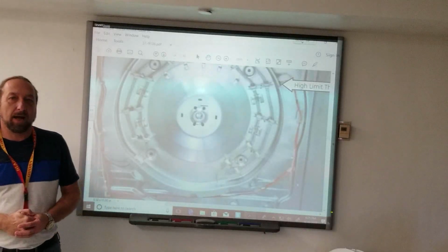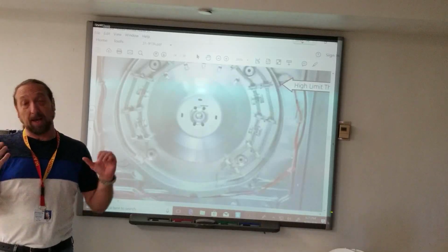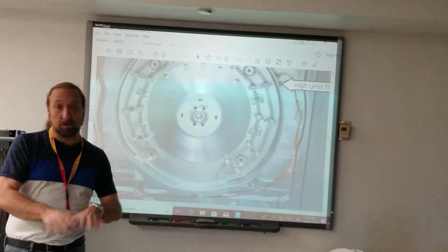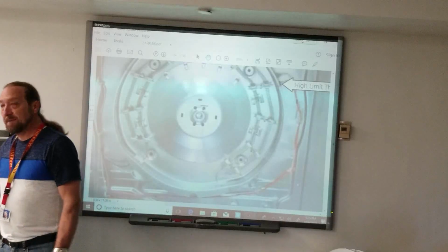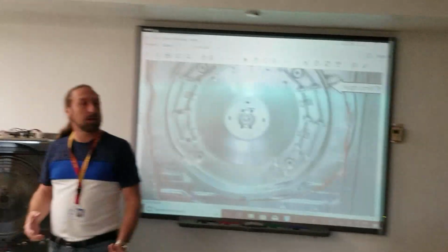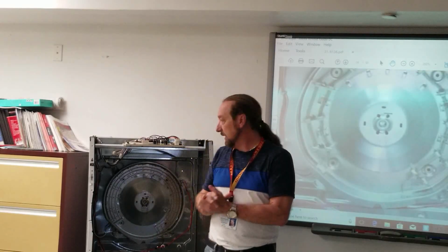High and low temperature. High and low temperature, but don't the thermostats control high and low temperature, or the thermistor tell the board, hey, it's 120 degrees or it's 160 degrees, shut off? Well, this is right in back of the drum, and if it radiates too much heat, even on a low temperature setting from the controls, the panels in the drum could get so hot. Some delicate clothing, like silk that women wear, could hit up against that hot metal panel and could damage it. So we can't have it get excessively hot. So on delicate clothing, we're going to put only one element on. And it's still going to reach temperature, it just takes longer to get there.